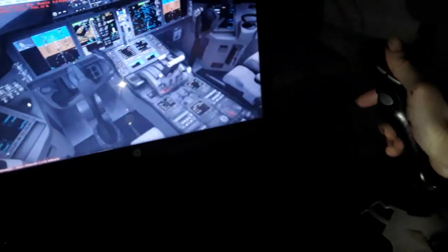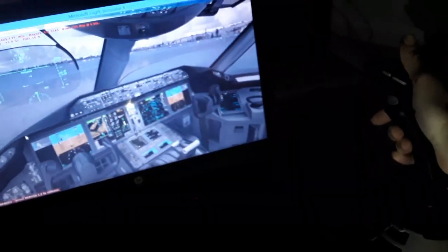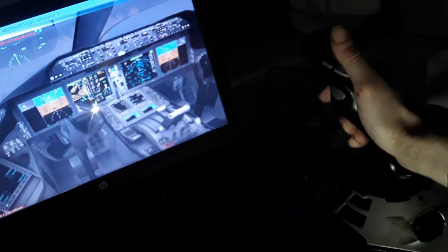A couple more minutes I will talk to you about the flight controls, how you use the side stick to control the elevator for climb and descent. Also make bank rolls using the ailerons and the spoilers, the rudder pedals, horizontal trim stabilizer, the thrust levers, flaps, slats, speed brakes, nose wheel steering on the ground, parking brakes. So I use the side stick, as you can see, for making climbs and descents. The elevator over here, make turns left and right, ailerons and spoilers, the rudder pedals.